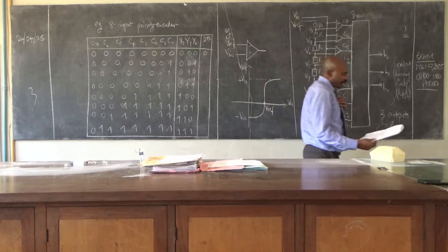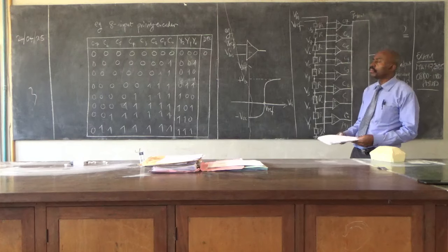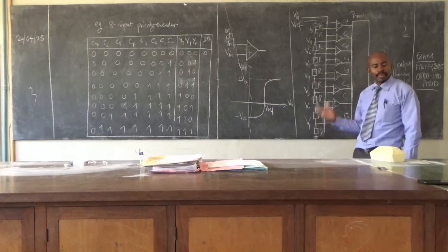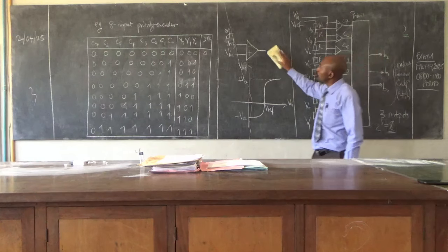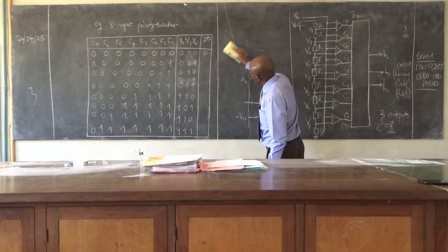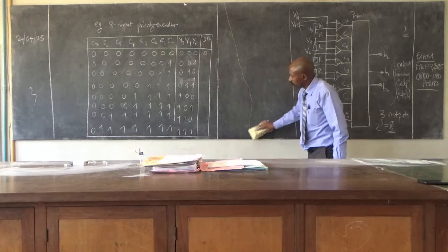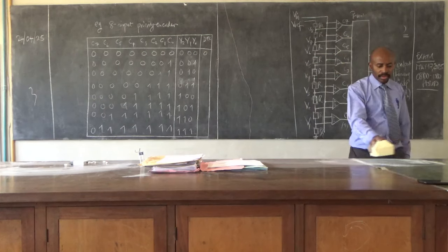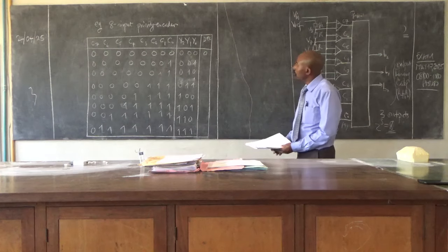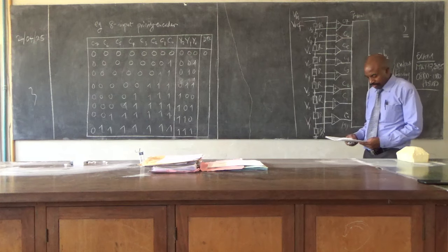The rest is how you conceive it in terms of the understanding of how these switchings happen. In the previous one, we said we use the FETs for the switches. After using FETs for the switches, the resistances for the ladder method are etched on a thin film and used in the circuit. So you see some thin stuff. You don't know what is going on, but then actually you have a whole bunch of stuff.